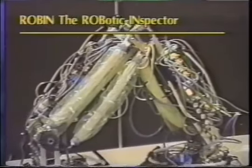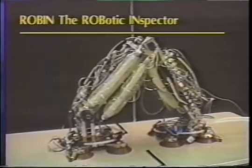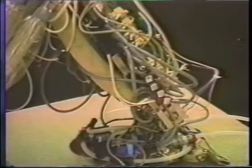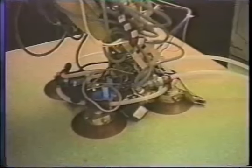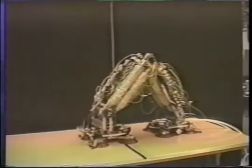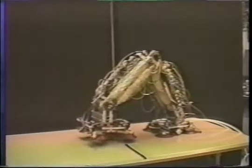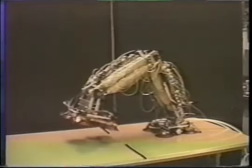In the future, we plan to add sensors and cameras to Robin that allow the vehicle to inspect a structure, but for now we're just concentrating on basic locomotion and control of the robot. Here you see the power-up sequence where the Robotuators are filled with air and vacuum pumps are activated in preparation for walking. Low-level control functions are performed by a network of onboard microcontrollers, while sequencing of the walking motion is handled by an off-board host computer.